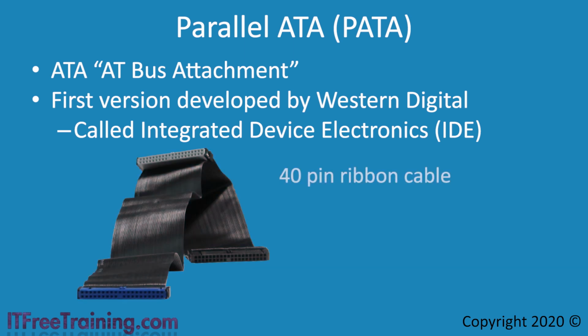The cable itself is a 40-pin ribbon cable. The ribbon cable is bulky. Due to the width of the cable, this can block airflow in the computer. Given that it works in parallel, 16 bits of data are transferred at once. The important thing to remember is not how many bits can be transferred, but rather that it transfers data in parallel rather than serial as modern computers do.